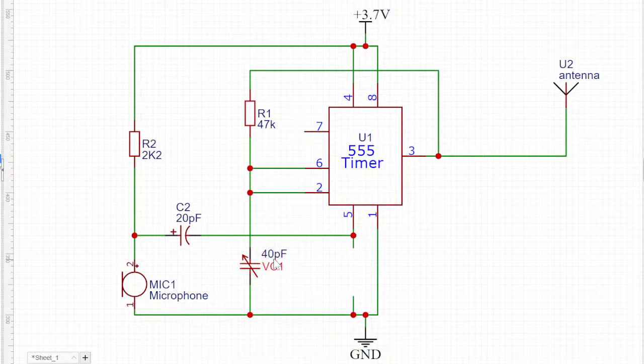level based on the value of this capacitor, so it's charging through the resistor, I mean, and then when the capacitor gets to a certain value, the two comparators will switch or toggle the output. One will cause it to be charging, and the other will cause it to be discharging, and it will go between 1/3 VCC and 2/3 VCC. So the frequency continues. Now, the maximum frequency you can get with a 555 timer depends on the type of